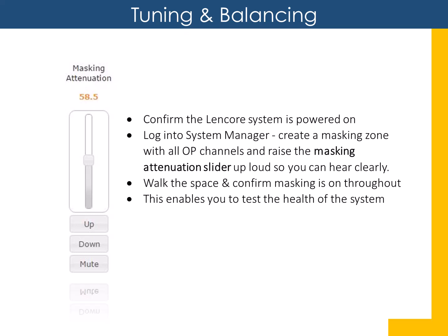Log into System Manager and create a masking zone with all OP channels. Using the masking attenuation slider, raise up the volume so that you can hear the sound masking clearly. Walk the space and confirm the sound masking is on throughout.